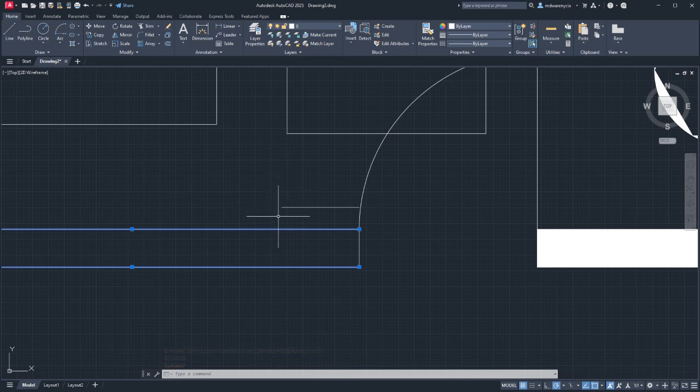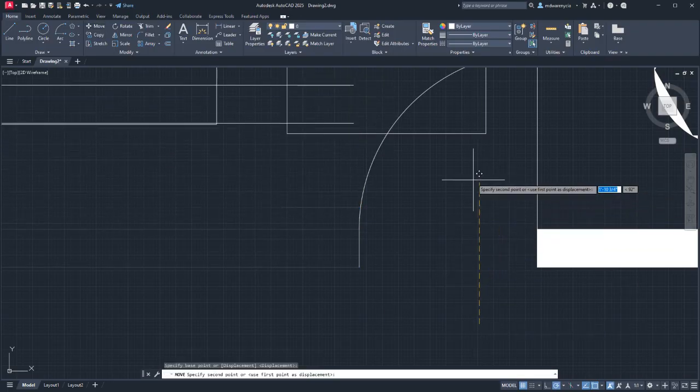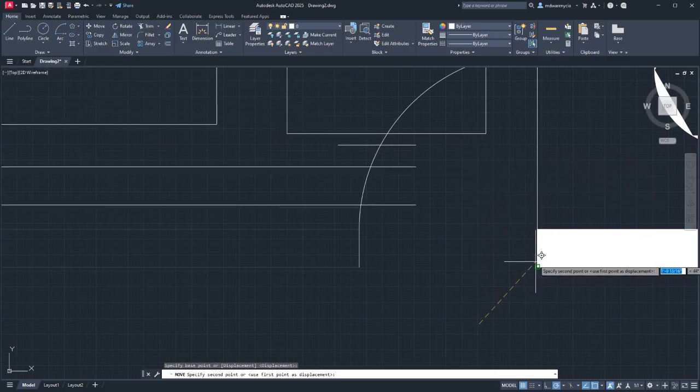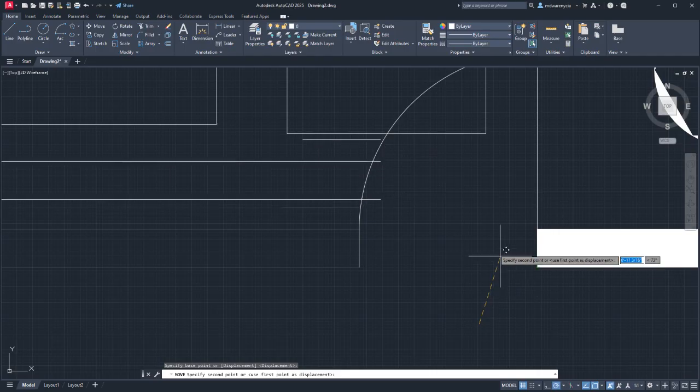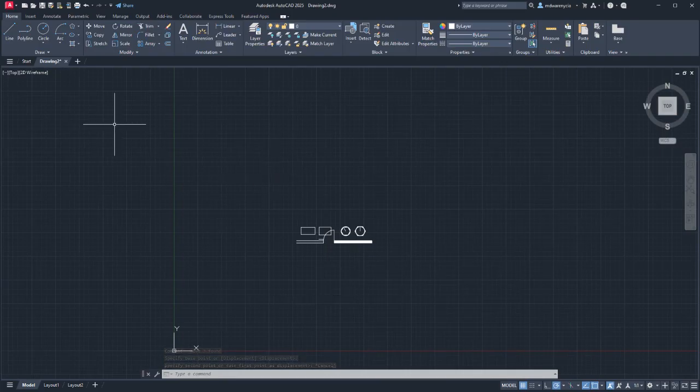Okay, so add to selection and then start the move tool. Choose a clear point of reference that won't get you into trouble. So if I was moving 45 degrees, it might snap to that here too. So even that I would consider too close. So find some clear space outside your model and use that as a reference.